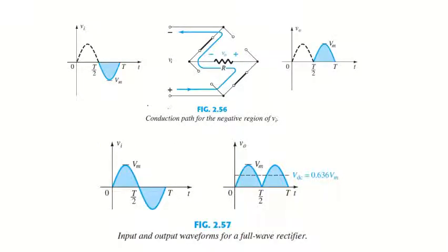Now in the negative half cycle, having potential minus Vm, these two diodes, this one and this one, are in the on state, whereas the other two diodes which were previously on are now off. So the current will follow this direction and you are getting the drop here.